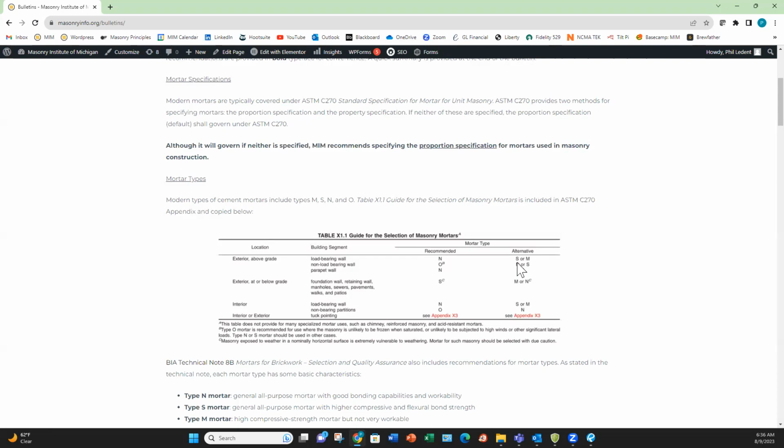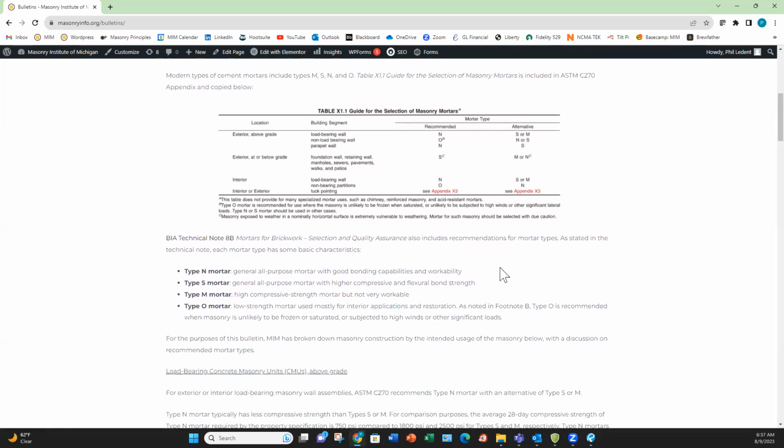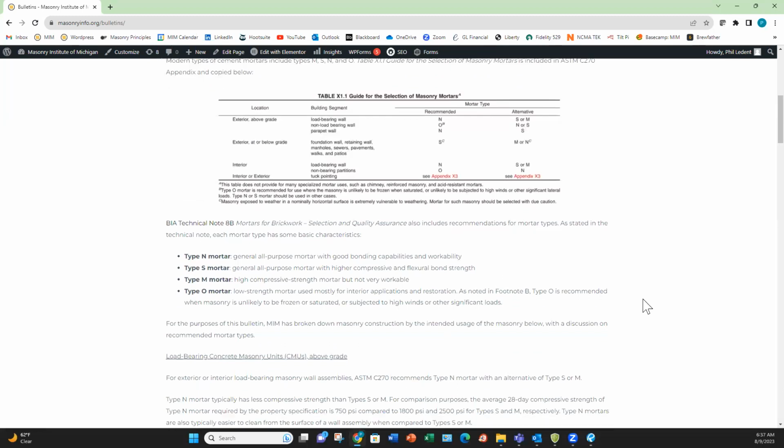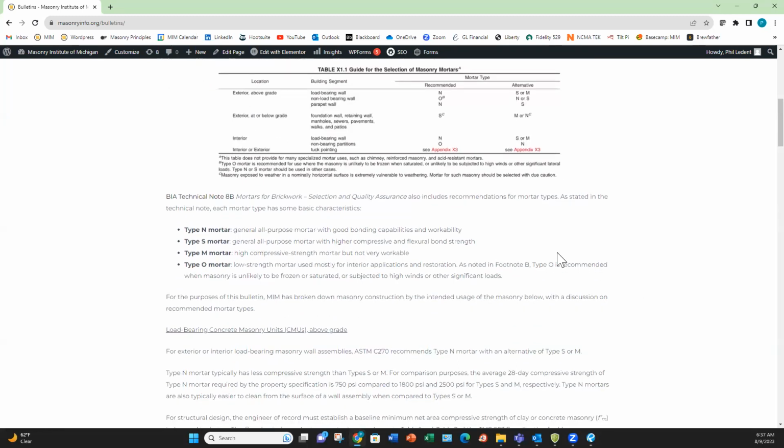We'll talk about this as we go through today. And I do have some recommendations that I'll give you from the MIM for projects, again, in Michigan. BIA, which would be our Brick Industry Association, does have a technical note 8B, which is mortars for brickwork selection and quality assurance. That has some recommendations, and this is a hyperlink that'll take you to that technical note. And the characteristics of our mortar according to the BIA: type N is going to be our general all-purpose mortar with good bonding capabilities and workability. Type S would be our general all-purpose mortar with higher compressive and flexural bond strength. Type M, high compressive strength mortar, but not very workable. And type O is a low strength mortar used mostly for interior applications and restoration.